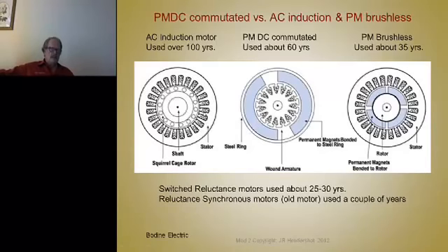So the current that flows into the stator magnetizes this circuit, and since it's an AC current, if you load this thing down, you're going to get some slip. That means you're going to induce some current to flow into the bars here, which is going to create the right polarity of flux to give you a torque due to the flux linkage of the ampere turns from this field with part of the ampere turns from this field.